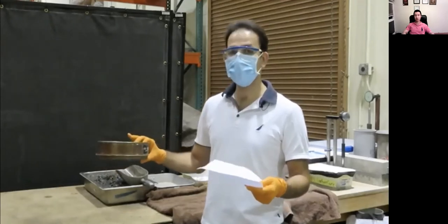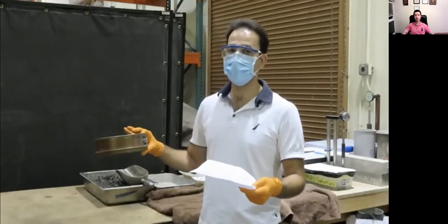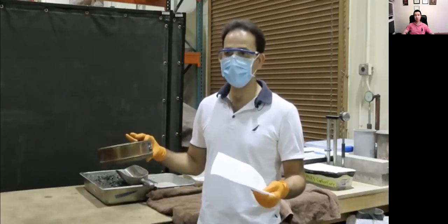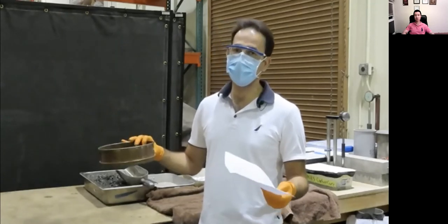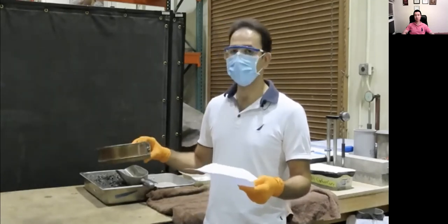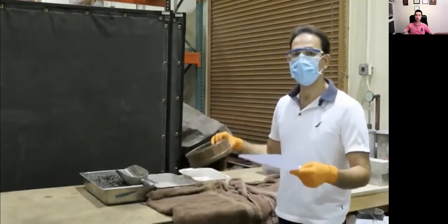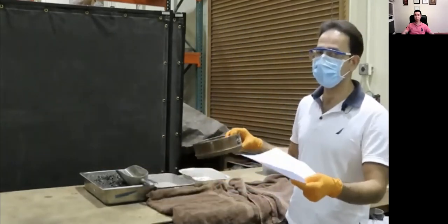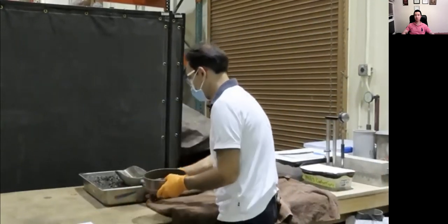I need more than 3 kilograms of the sample. I mean the saturated surface dry sample. So I need to prepare a little more than 3 kilograms. So I'm not worried about the weight for now. Just sieve it, put it on the towels, dry the surface, and try and error to get a little higher than 3 kilograms. So what I'm doing now,